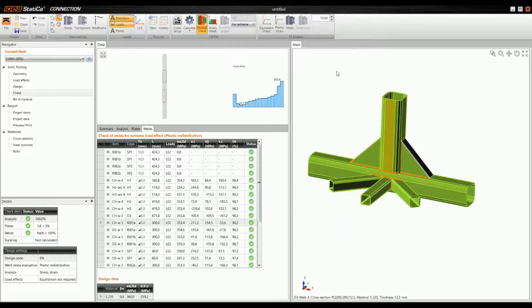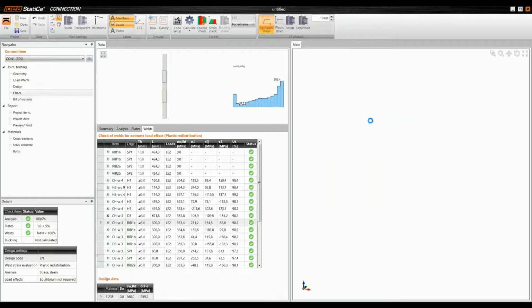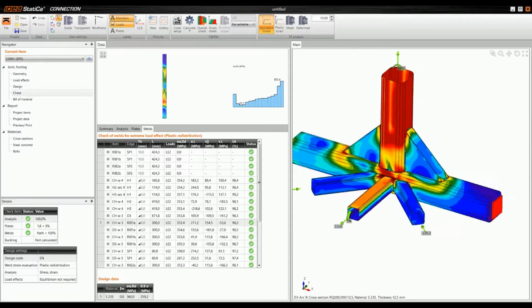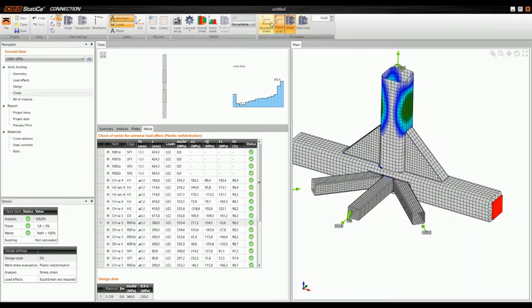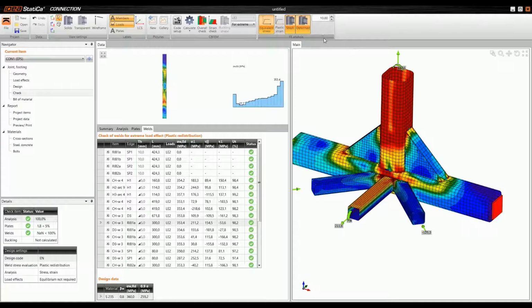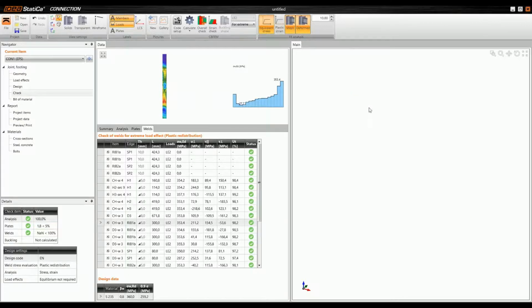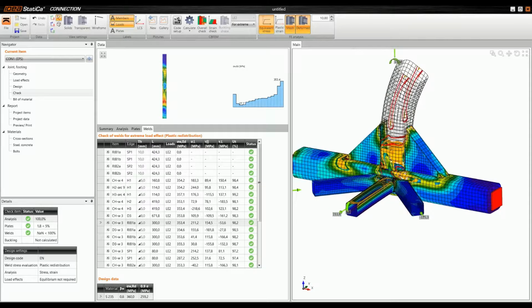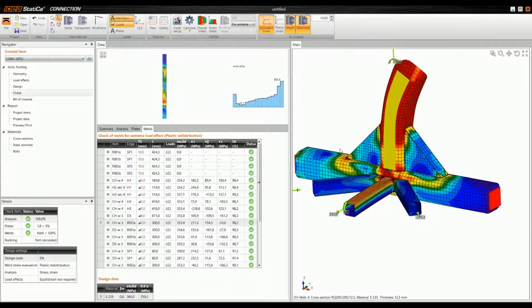Okay, so then you can, of course, look at the equivalent stress and other displays here in the joint, about the plastic strain, turn on the mesh and see the deformation. Okay, this is bending pretty nicely from the moment here. So this is now quite stiff because we added these triangular boxes. So we can see how nicely it is working actually.